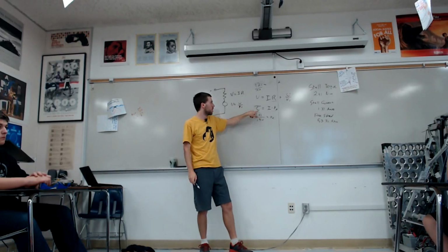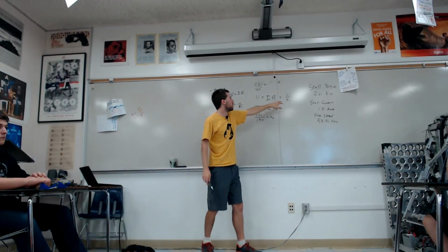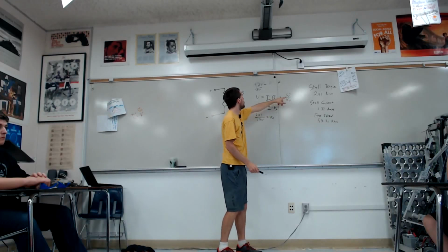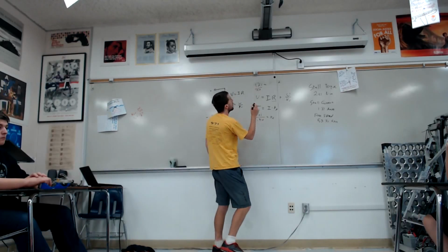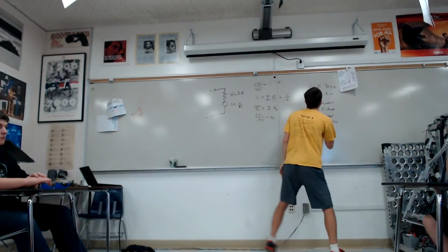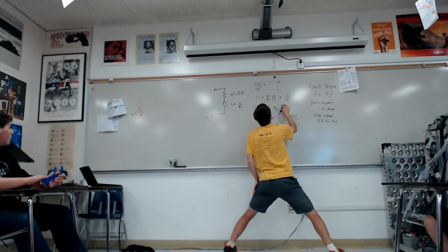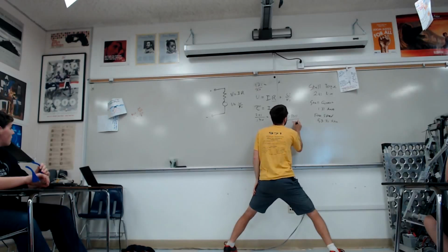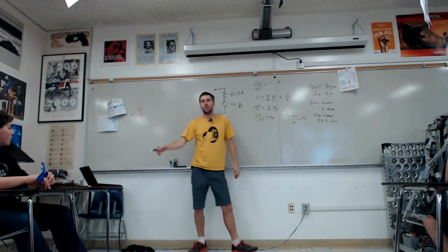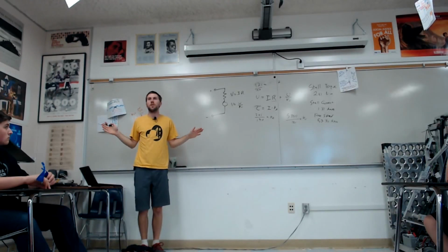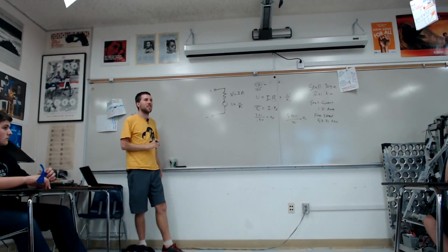If our torque is 0, by this equation our current is 0, that means this term drops out. So our voltage equals, and we can then solve this. So our omega over our voltage is KV. So we would say, are people following what we just did here? I see some nods, that's good.